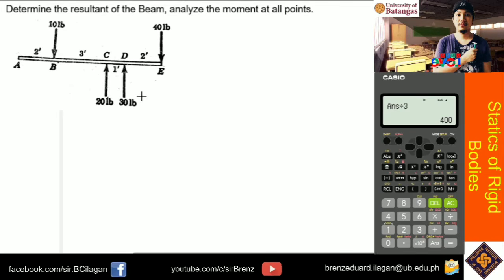Okay, so i-analyze muna natin. Again, let's solve for the resultant. Kung saan ang resultant mo will be just equivalent to Ry, or just the summation of all forces in Y direction. So, summation mo lang yan. So, you have here negative 10 since pababa. Followed by, you have 20 since pataas yan. And then plus 30. And then minus 40. So, mapapansin nyo, the value of the resultant will be equivalent to, so negative 10 plus 20, so 10, plus 30, so 40, minus 40, so this is equals to 0 pound.